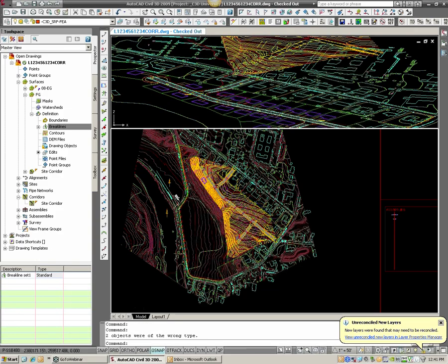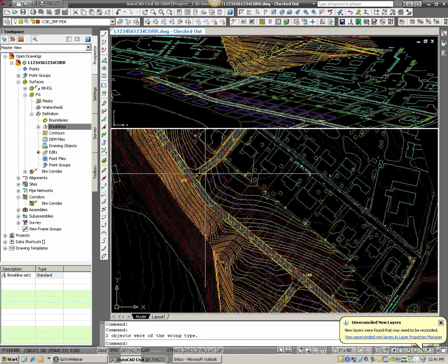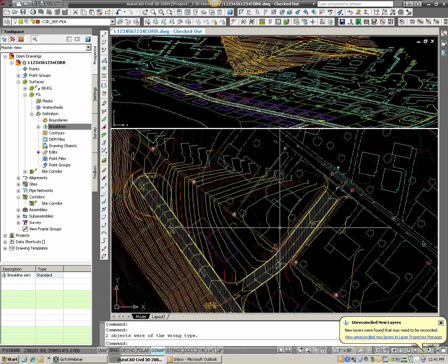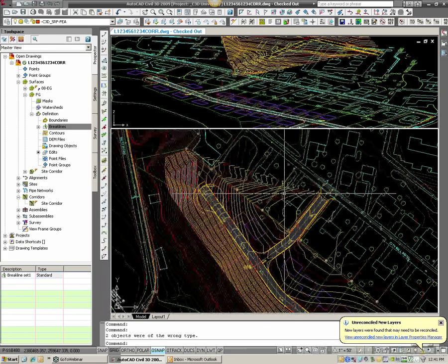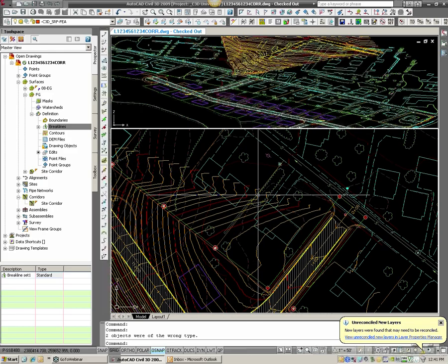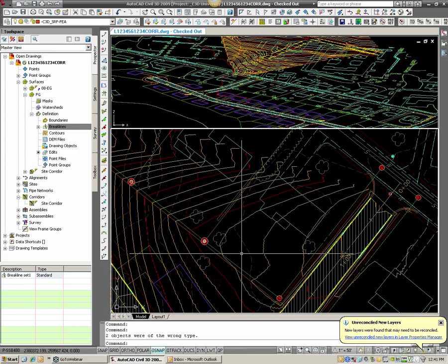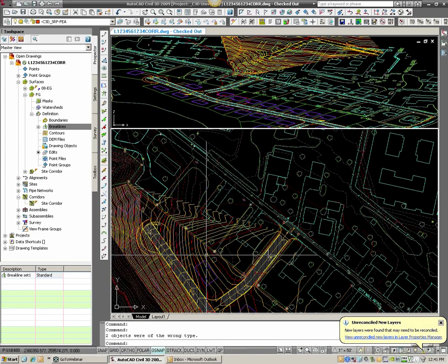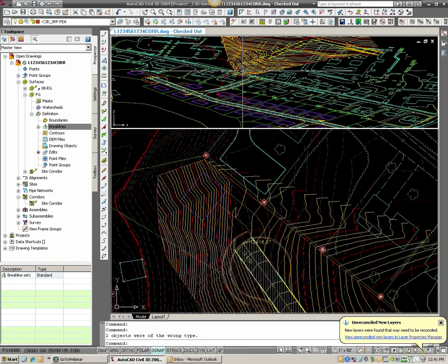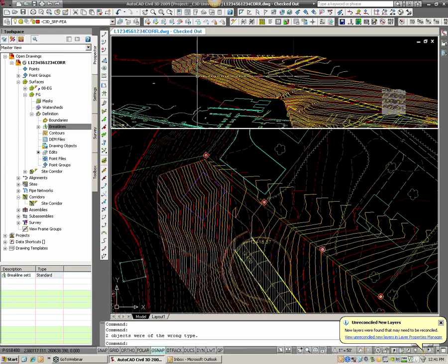Hit OK, and now you can see we're filling out my site farther and farther here. Okay, still in the hatchet stage, still swiping through this thing with a hatchet. Another thing I need to do is add a boundary. This is pulling all across these guys' lots, and if we start grading this guy's house out, he's not going to be too happy. So I want to add a boundary to this. The easiest way to do that is to use this feature line that I already have. This feature line is all the way up here at grade.